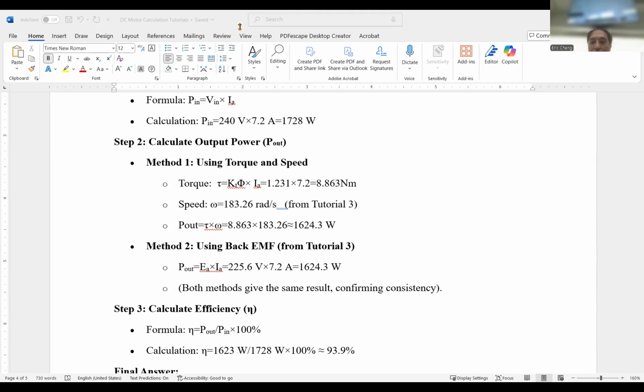So what's the normal current? The normal current is 15 amp. So with 15 amp, we have about 1.8 as the ripple. That means the top will be 15 amp plus 1.8, and the bottom one will be minus. So there's an up and down. We call the middle the average. We have this top part and bottom part. We usually assume the current is a straight line here and then goes up and down. And this amount is our peak to peak, the so-called delta IL. That's how we get that.